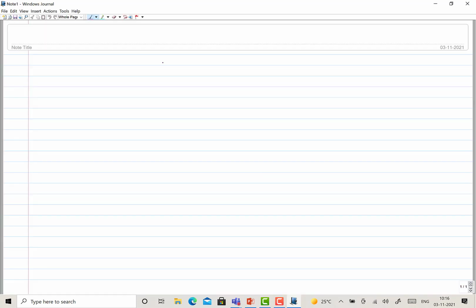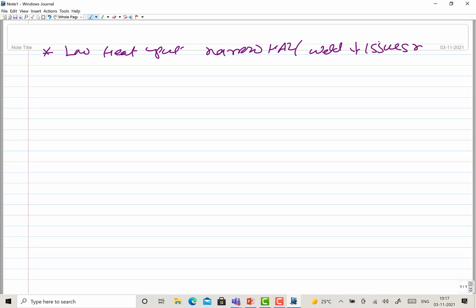So there are so many positive sides as far as electron beam welding is concerned. Like one, I said it's very low heat input because of the high power density process, leading to a very narrow HAZ and weld size, and because of this you have reduced issues related to the heat input, because you are providing very little heat.